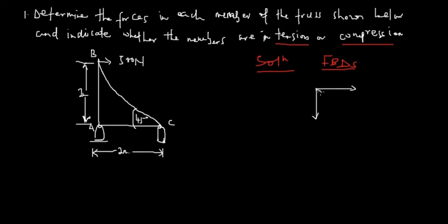Okay, so this is moving upwards, and this is moving in this direction, so we have 500 newtons. This is for B. We started at B because that's where we were certain of a force which was already given. So we have FBC, because this is B and C, and then most definitely this would be BA, so we have FBA. This is very simple.